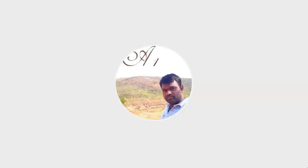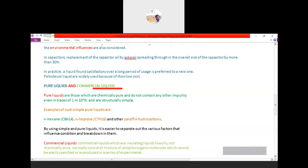So we have cable oils, capacitor oil, and silicone oil. The breakdown strength at 20 degrees centigrade with a 2.5 mm gap, when we test it, is 15 kV per mm for transformer oil, 30 kV per mm for cable oil, 20 kV per mm for capacitor oil, 20 to 25 kV per mm for askarel oil, and 30 to 40 kV per mm for silicone oil.